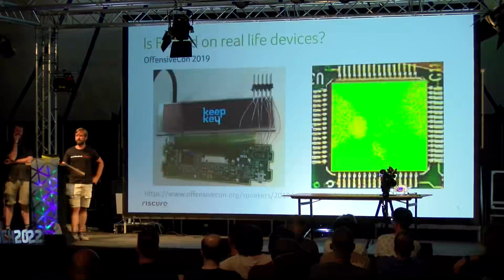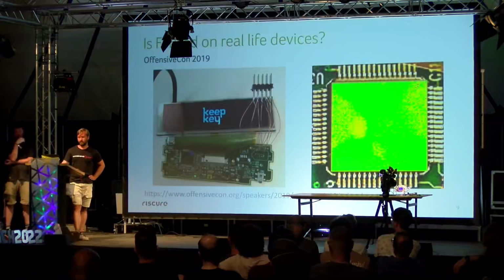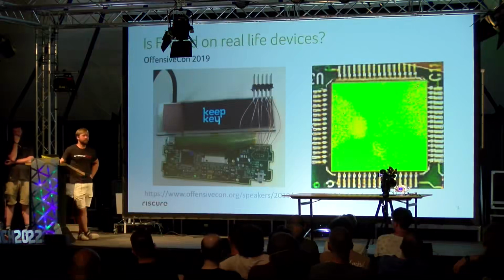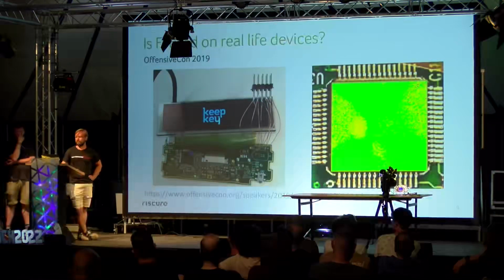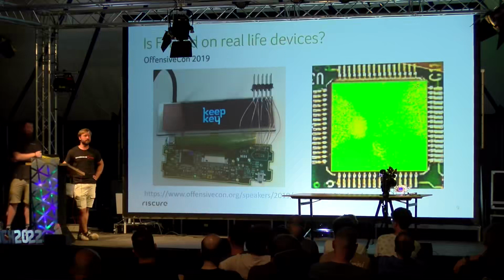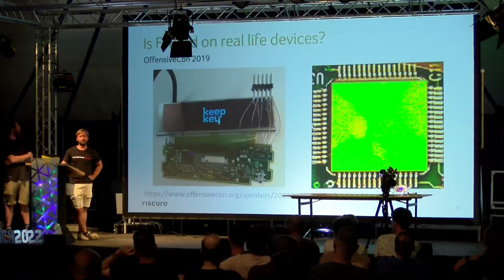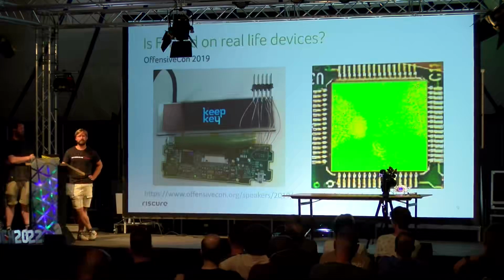One example of what we've done in the past is glitching a Bitcoin hardware wallet. It runs a simple microcontroller, an STM32 chip, and we used EM fault injection. For this device, it was open source code, so we could look at the firmware, which is always very nice. Even when you do physical attacks with hardware, it's nice to know what the software does.